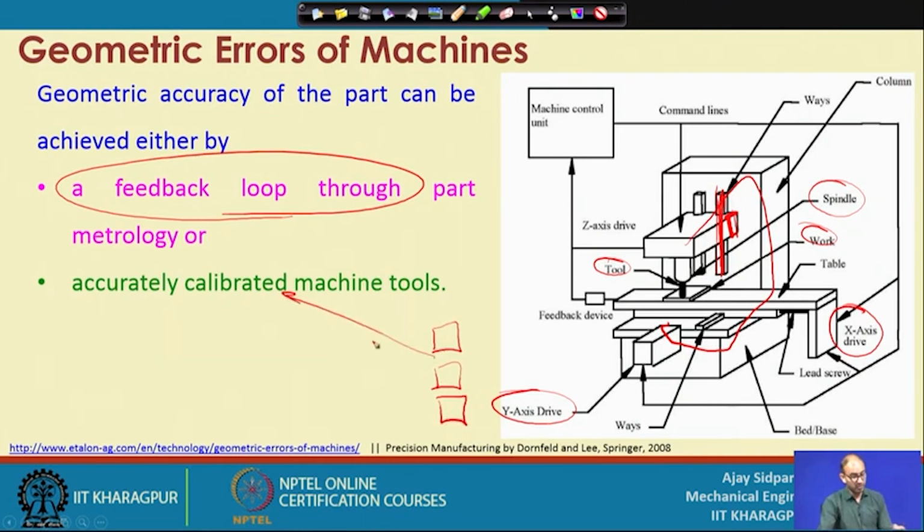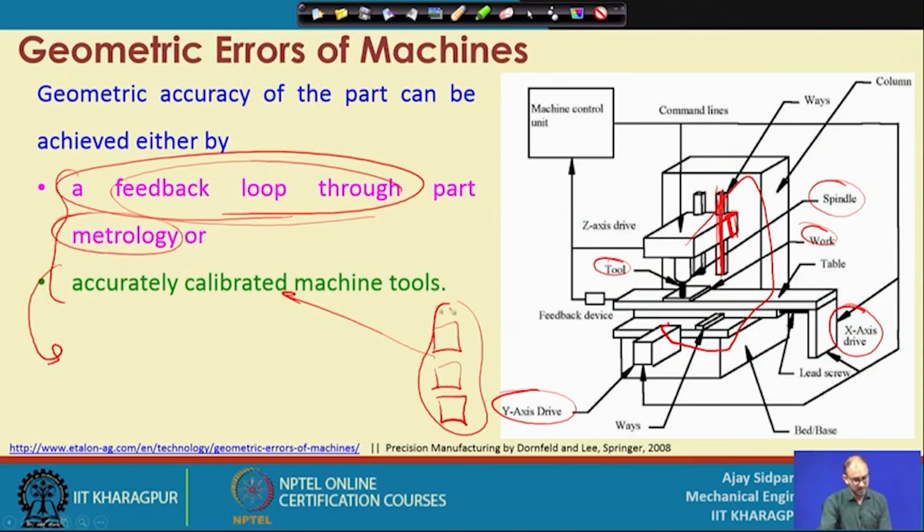You do not have so much deviation that will reject the part, or deviate the part, even if all the input conditions are constant. So, if both things are there, it is more perfect, much better than anything else, because you are getting feedback also through the metrology part. Metrology part means you can measure the surface roughness also. If you have a roughness tester located here, or a camera directly, you can actually analyze the tool wear also, and the part's geometry.